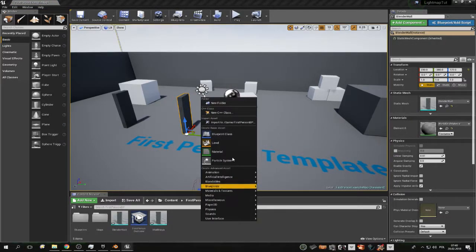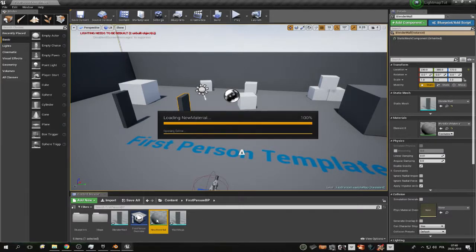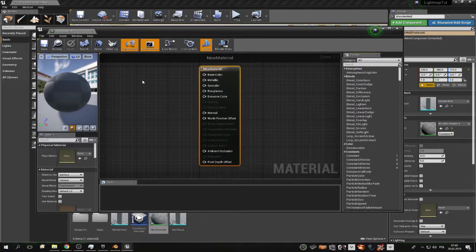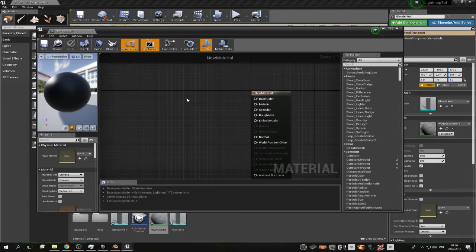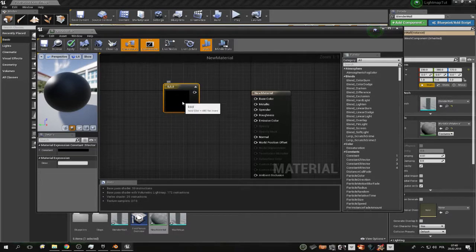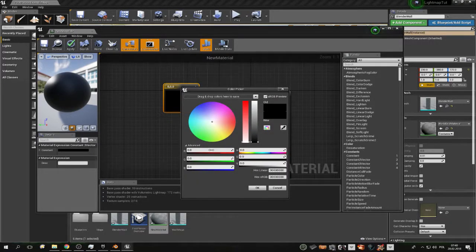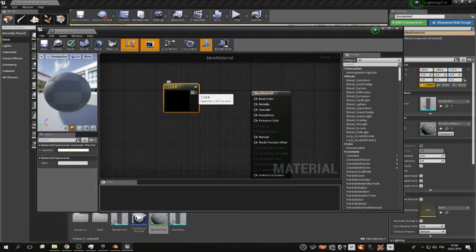Okay, but we will need also a basic material to test things, just the same material as there. Yes, you can press and keep pressed 3 on keyboard and then left click and this node will show up. And we can choose our color and it was 11.8 I think it was in the tutorial.